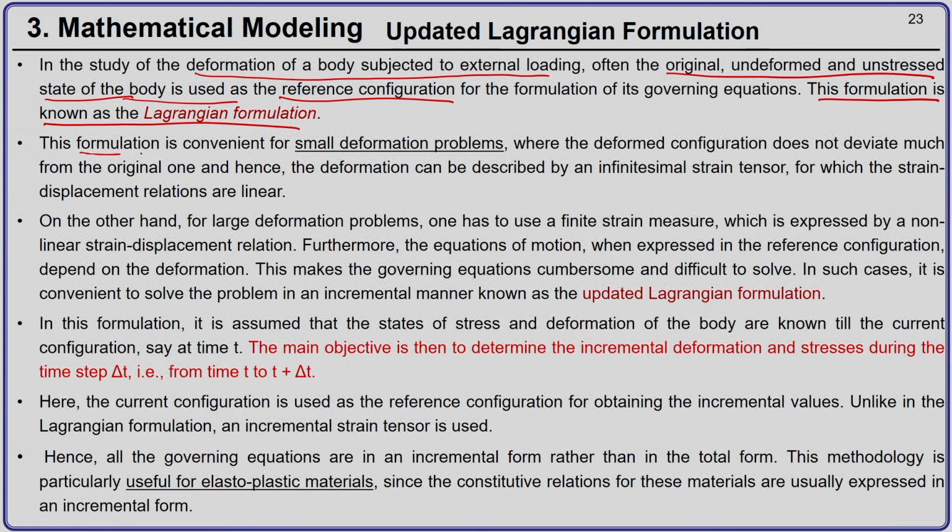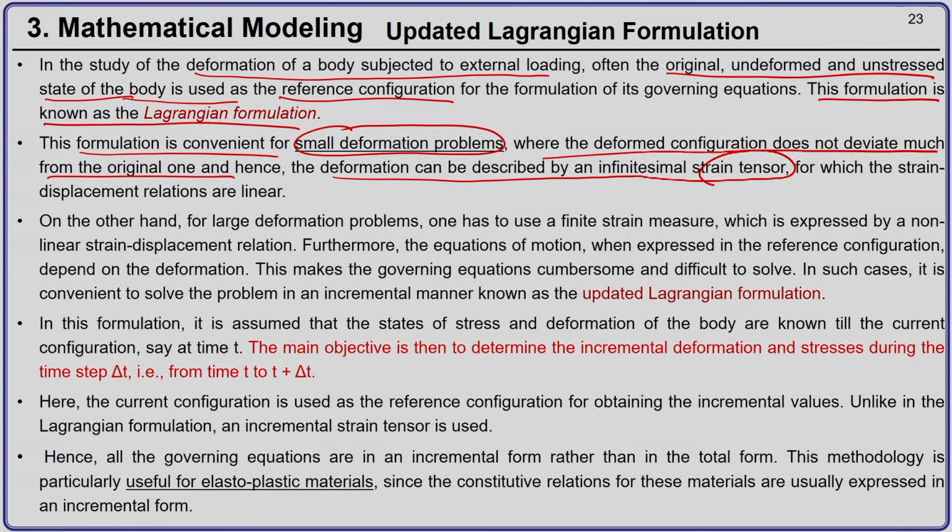However, this formulation is only convenient for small deformation problems, where the deformed configuration does not deviate much from the original one, and hence the deformation can be considered by an infinitesimal strain tensor, for which the strain displacement relations are linear.